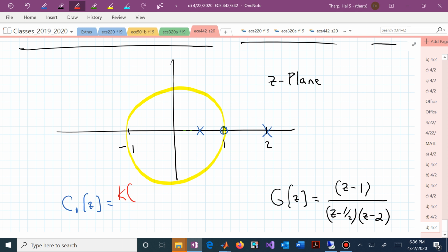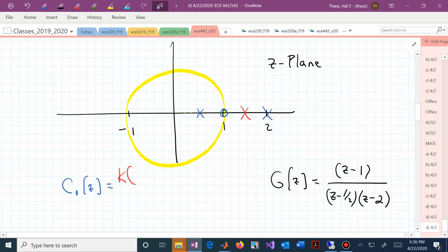And how can we make that happen? Well, one way we can eventually get off of that segment is to in fact introduce an unstable pole in our controller, and because we're, I hope at this point, very comfortable sketching a root locus where we have 2 poles to the right of a 0, what if we canceled that?